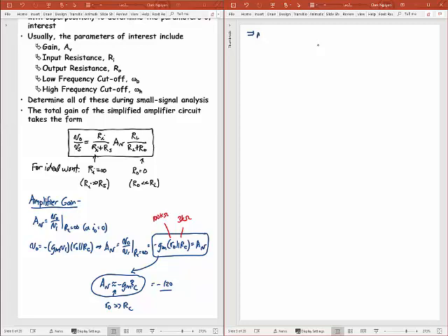So I can write that my maximum gain occurs when RC equals infinity. But remember, my gain, I can't just use this equation for RC. My actual equation then boils down to this one here. So that means that the maximum gain happens when the RC is much greater than R naught in this equation here, where I'm pointing on the left side. Right? So the maximum gain then turns out to be equal to minus GM times that R naught.